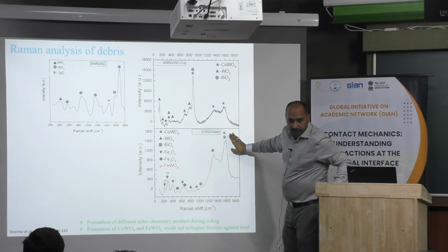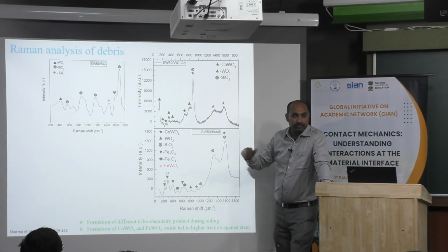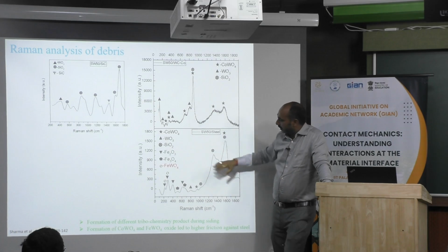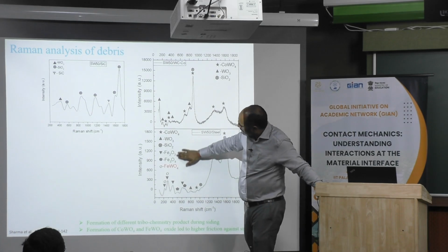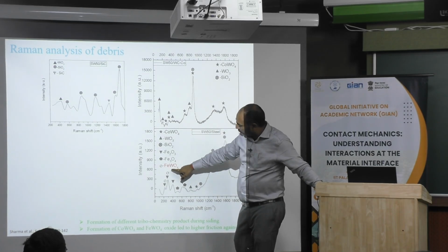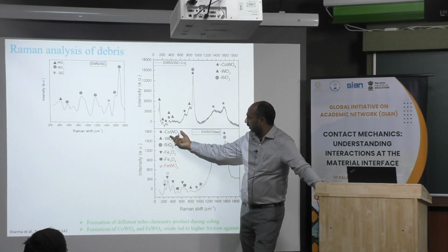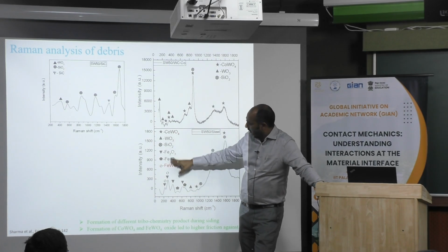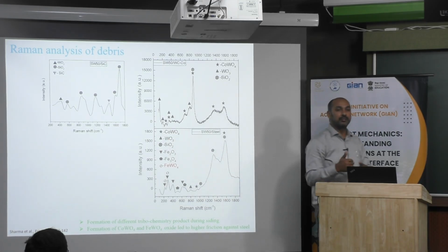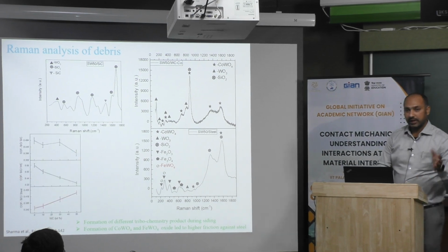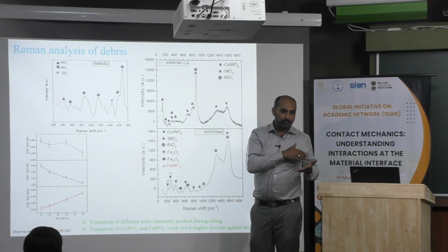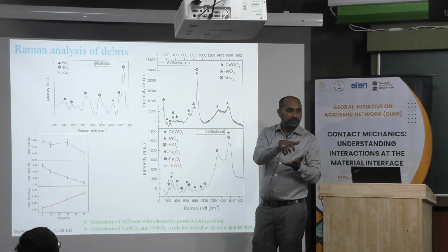Now if you go for steel, here it is very important, which will confirm why in case of steel we actually get an increased amount of friction. The byproducts forming are FeWO4 and CoWO4. With increased amount of tungsten carbide, this formation will increase. Yes, and they have high hardness as compared to steel. So now they will abrade. We understood that if you go with the harder coating, they will abrade and friction will be more.